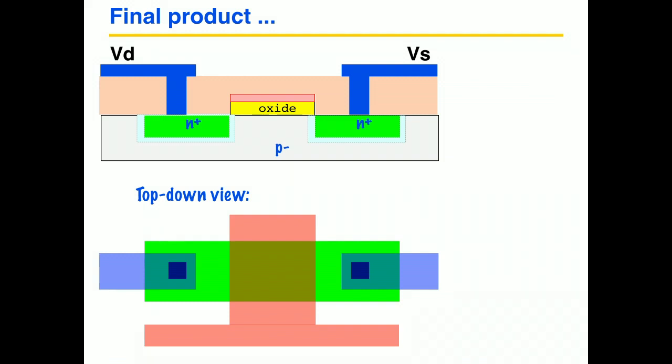If we want to go to a very high number of metal layers, like 10 or so, what they'll do is actually smooth out the whole surface of the wafer in between adding metal layers by polishing it mechanically and chemically to get it very smooth, and then grow another oxide and put another layer of metal and then smooth it out. And as long as you keep smoothing it out, you can go to 20 layers of metal if you need it.